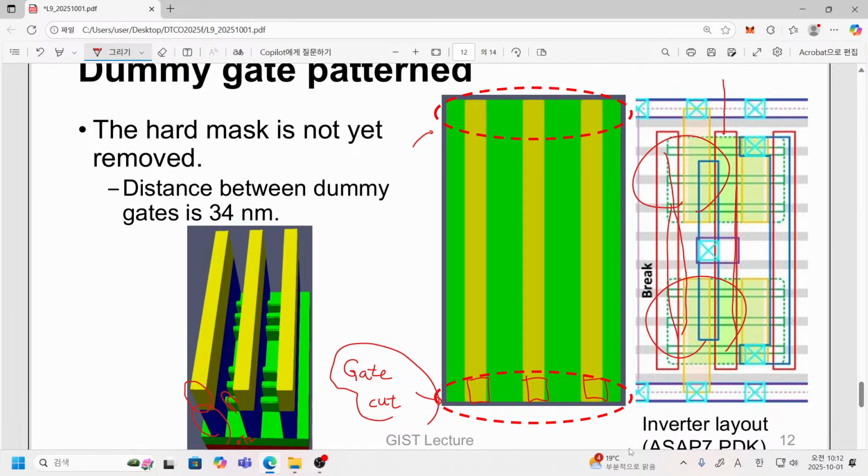The natural question is, instead of drawing and erasing, why don't you just draw some segments only for the required fields? For example, for this part, do not draw it. But the point is, how did you draw this 54 pitch line, or this 27 pitch line? You have used, not directly, but SADP or SAQP. In that case, you have to make a sidewall.